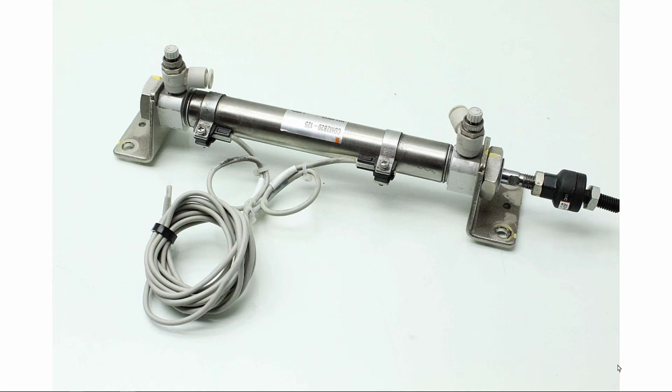That's because you want to know for sure that it retracted so it's not colliding with other components out in the workspace. And then you're just going to have to use a little timer to say after 1 second, we're assuming the cylinder extended, and it's a time-based event instead of a true event where something actually happened physically.